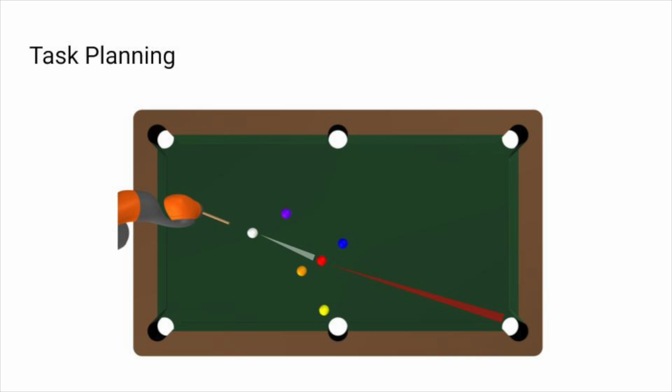We define the angle of our hit to be relative to the x-axis in the world frame. We calculate the allowed angular deviation for every pair of ball and pocket combinations if the shot is feasible. This calculation follows several steps to narrow the range of allowed angles to ensure a feasible shot while avoiding collisions. We then select the greatest allowed angular deviation as the shot to make and take the midpoint of this angle range that will sink the ball as the angle at which we want to hit the ball.